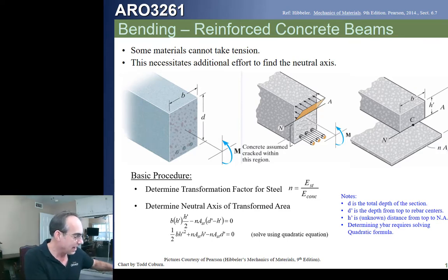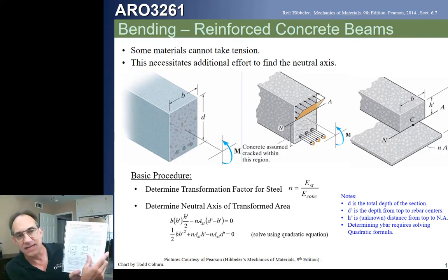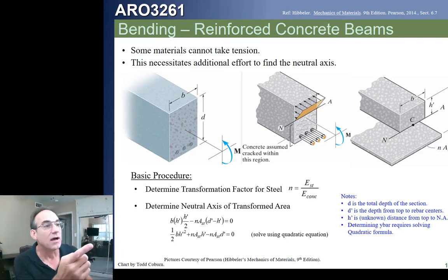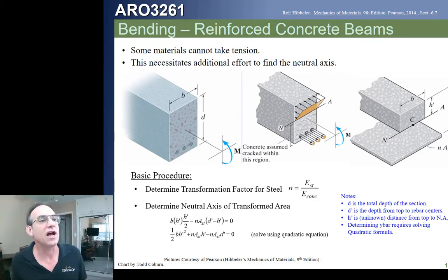If you look at your handbook, section 6.3, I have added quite a bit of detail on how to calculate where this is. A lot of these textbooks will show the stress distribution in the concrete as a triangular one, as shown in this middlemost picture. Actually, the analysis that they're using isn't using a triangular distribution at all. It would be fine to use a triangular distribution, it only makes it slightly more complicated.